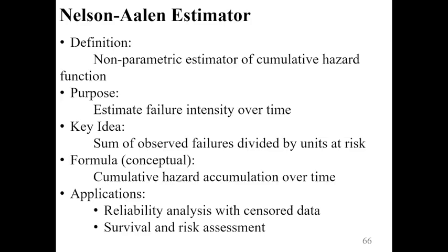This produces a stepwise estimate of the cumulative hazard, which increases as time progresses and more failures occur. The Nelson-Aalen estimator is particularly useful when dealing with censored data and is often used alongside the Kaplan-Meier estimator to provide a more complete understanding of reliability and failure behavior.